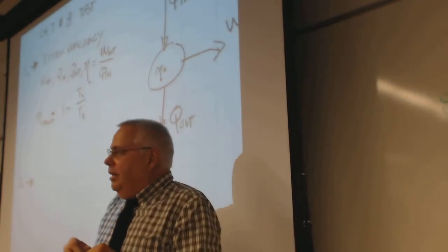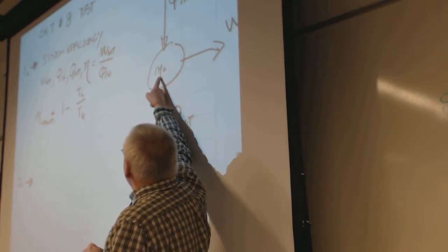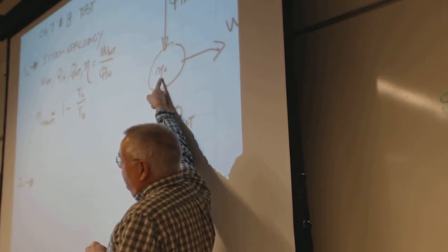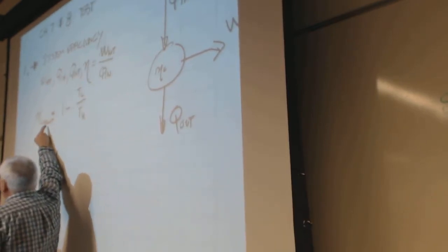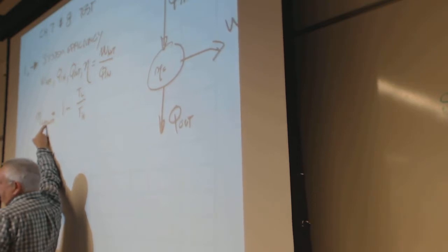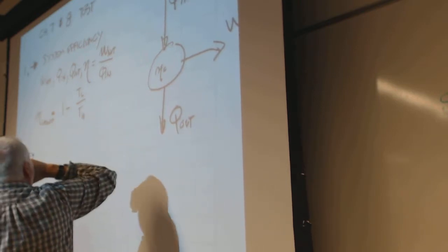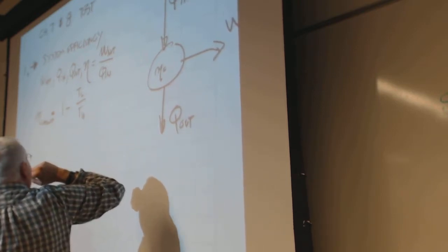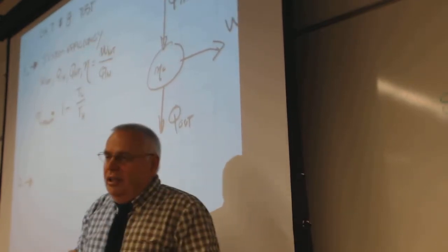The whole thing about entropy and isentropic processes, if you came up with an efficiency here of 25%, and the process here, Carnot efficiency said you had 50% efficient. There's a difference between these two. So the overall efficiency, including this limit, is built into here, and you have a chain of efficiencies.